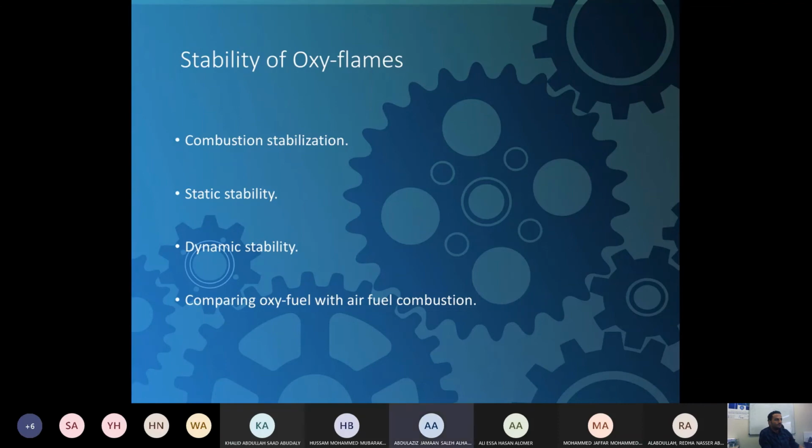Dynamic stability is the flame stability in terms of high sound pressure, which is generated in the combustion system and coupled with acoustic fluctuations. This is also important, as it can cause wear to the parts of the combustor, which, moving with flow gases, can damage the gas turbine components.